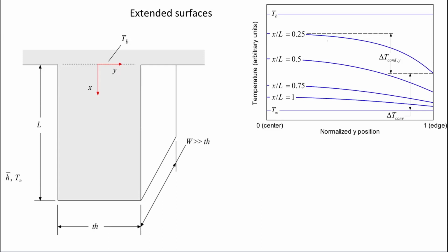So for an extended surface, the idea is that if I'm a little bit of heat and I'm at the base of this fin, right? So this is a big piece of metal or small piece of metal, and it's attached to some base. An extended surface is just an approximation that allows us to model something as 1D. If I'm a little piece of energy right here at the base, and I'm going to move out to the surroundings, the surroundings being out here at T infinity, let's say, it's no longer true for this type of surface that I would just move in the x direction. You may have some little unit of heat, if such a thing exists, get here and then go off to the surroundings. But for a lot of the heat, it's going to go out and be lost to the surroundings off the edge of the surface.